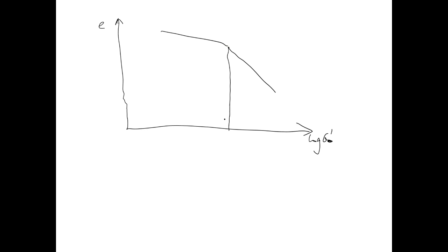So you don't need to worry about it. Normally the horizontal axis will be sigma prime in log scale, and this is the void ratio, for the settlement actually. But you don't need to worry about the axes. You only need to know the relative position of sigma P prime. Once you calculate sigma P prime, you know it's the intersection between the 2 line segments. Is that clear?